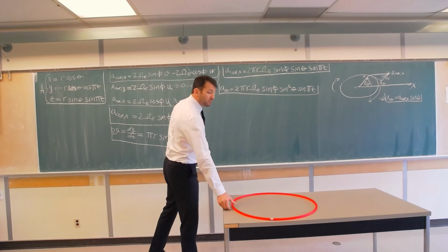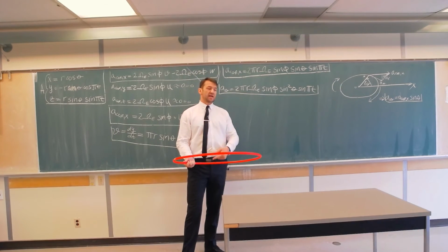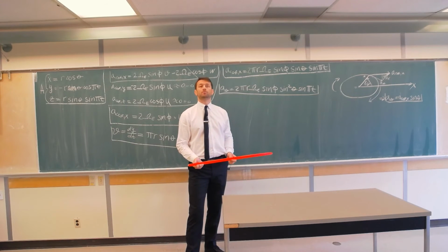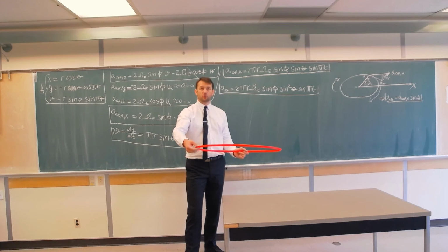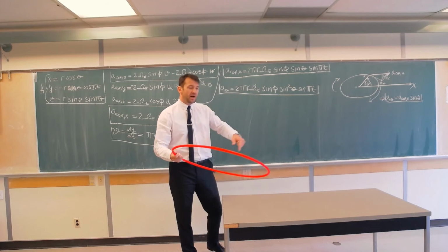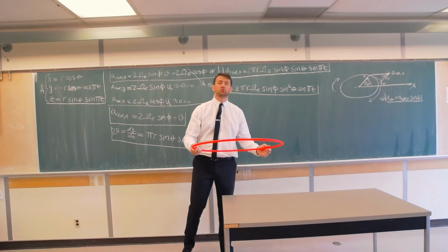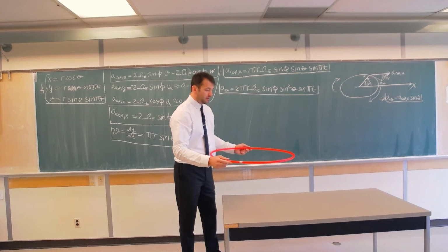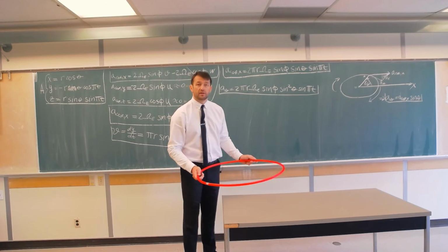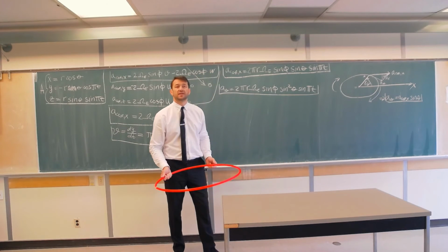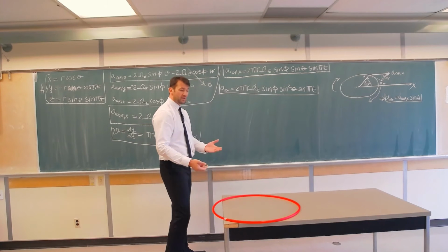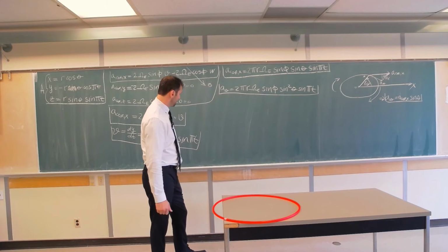Now, I didn't mention, but why would we use water? Why not use air that is already inside? Well, water is incompressible fluid. And that means if one parcel of water starts moving, all parcels have to have the same drift velocity. For the air that is compressible, that doesn't have to be the case. So that's why I'm saying we can have water or some other liquid inside.